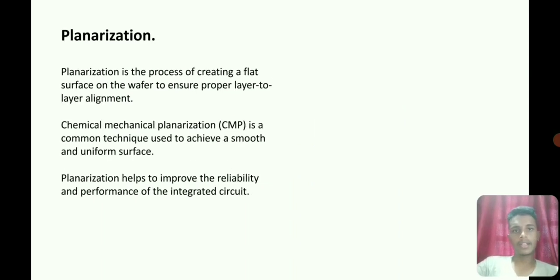And the planarization is the process of creating a flat surface on the wafer to ensure proper layer to layer alignment. Chemical mechanical planarization is a common technique used to achieve a smooth and uniform surface. Planarization helps to improve the reliability and performance of the integrated circuits.